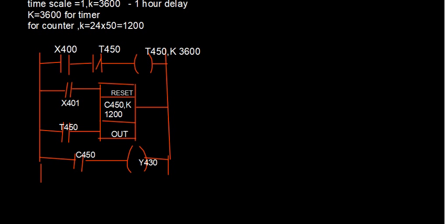You can even write the instructions here for this particular ladder diagram. So please try writing the instructions. The first instruction happens to be LD X400, as you know.